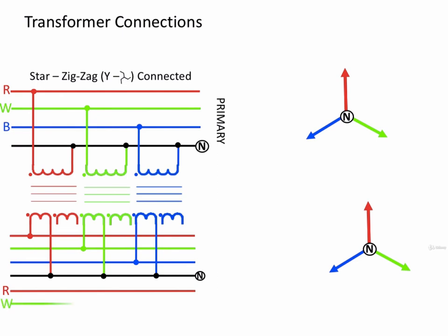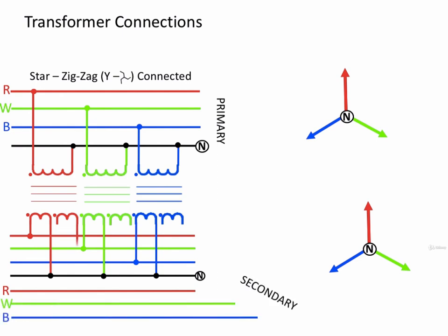The red unspotted terminal of the secondary is connected to the red system lines, buses, etc. The other red spotted terminal is connected to the spotted terminal of the white terminal of the other secondary winding. And added to the existing vectors would look like this.